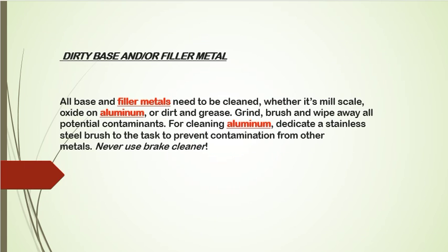All the base metal and filler metal need to be clean, whether it's mill scale, oxide on aluminium, or dirt or grease. Grind, brush, and wipe away all potential contamination. For cleaning aluminium, dedicate a stainless steel brush to the task to prevent contamination from other metal. Never use brake cleaner. If you use brake cleaner or other metal, there will be contamination with the aluminium, and defects will be produced.